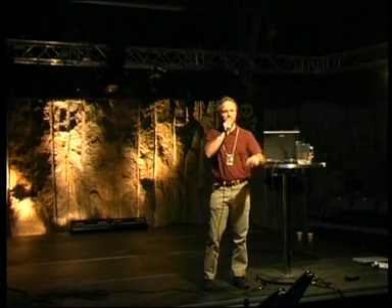So you just have to make sure that your sampling period divides this number, because then you can have a fixed number of samples per vertical blank, and you can just fill up this buffer at the same rate as the playback plays it, without having any audio interrupts.